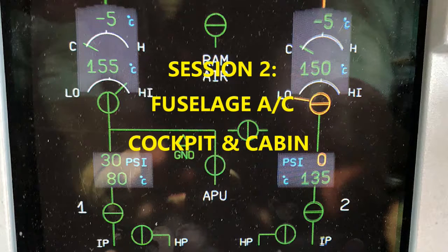There are different modes. I'll get into pressure schedules in a little bit. I just wanted to cover the monitoring system first. The abbreviation is CPCS. CPCS is Cabin Pressure Control and Monitoring System. That whole system is making sure that the pressure is where it needs to be, regardless of the attitude of the aircraft. So it's automatically controlling the quantity of air going in and out through the outflow valve. There's also a manual system which controls the CPCS in case the automatic system is not active. And you have your safety valves as well.